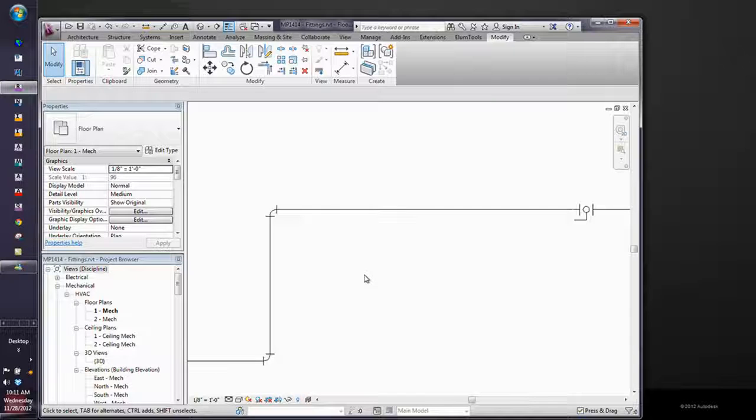And we know that everything else looks exactly correct, right? How about that ball valve? That one doesn't look like anything that I use in there. I use isosymbols, and that's not an isosymbol, man. The isosymbol's got two triangles with a circle in the middle of it, right?